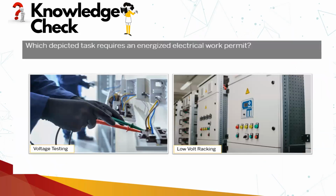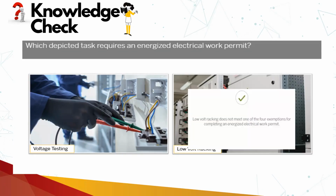Okay. This type of question you can expect in the exam. Which depicted task requires an energized selective work permit? On the left, he's performing voltage measurement. On the right, the low voltage racking in and racking out. So we have seen that voltage testing on the left does not mandatorily require an energized electric work permit, but the racking in and racking out will require that energized electric work permit.